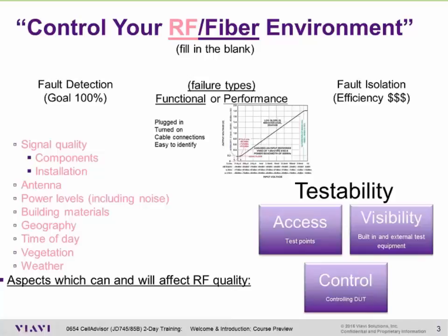And the third part of testability is controlling the device under test. Controlling the device under test is similar to testing your radio or your stereo. You're oftentimes going to turn down the audio, listen to the audio quality at a low volume, make sure there's no hum, static, crack, pop, and then turn up the volume and see what it sounds like. Well, the same thing should also be applied to many of your transmitters. You should have the ability to use OCNS or AILG. These are test modes of your transmitter that allow you to push it to full power, to look at signal quality or to look at possibly pin issues that could affect your receive.